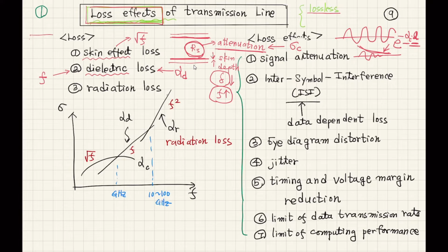If this is the transmission line, we're going to have dielectric material, but it will have a real term as well as an imaginary term, and the imaginary term will represent the loss, and it is coming from the loss tangent. In the electromagnetics book, it is represented by loss tangent delta.